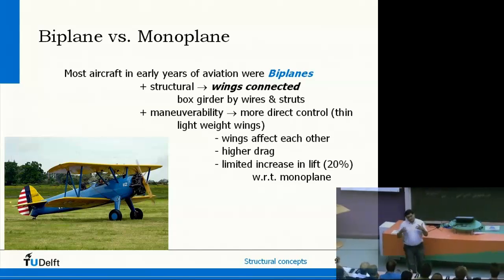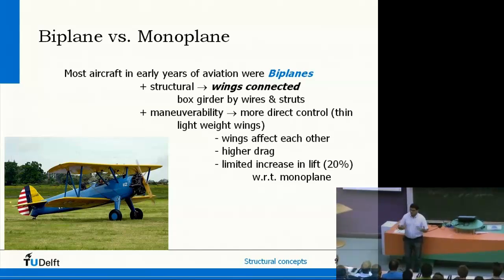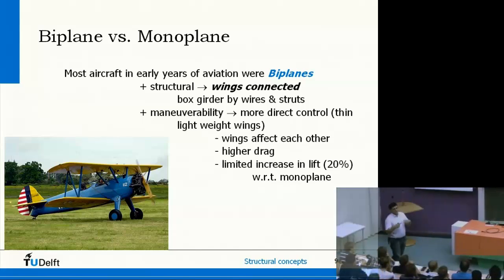So the strength is related to the maximum load a specific structure or material can take. And the stiffness is how far it deforms during a certain load. If I have a very little deformation with a particular load, then I can say, okay, this is a very stiff, a very rigid material. If I have a very large deformation with the same loads, then the material is flexible, it's very unstiff. That's the difference between strength and stiffness.